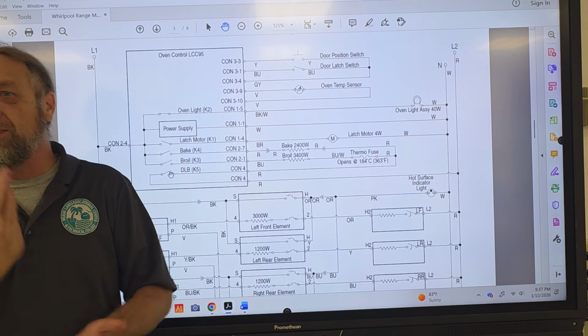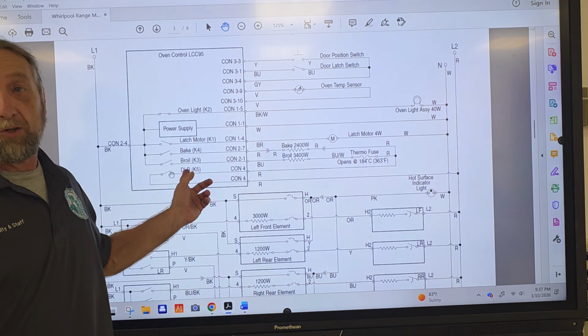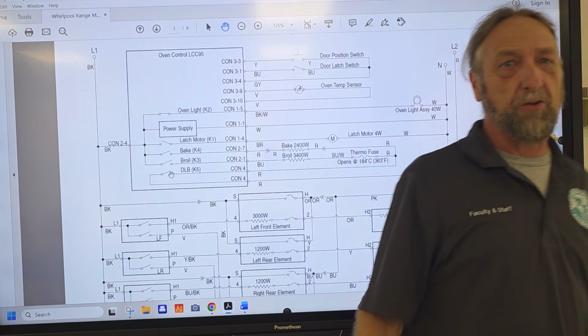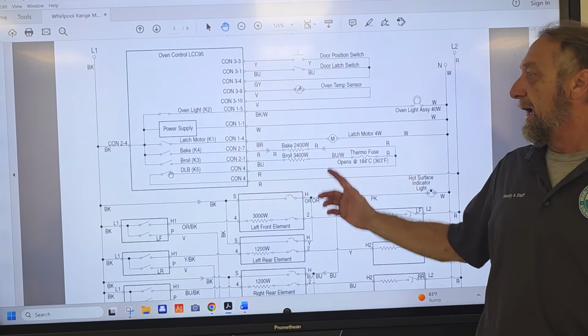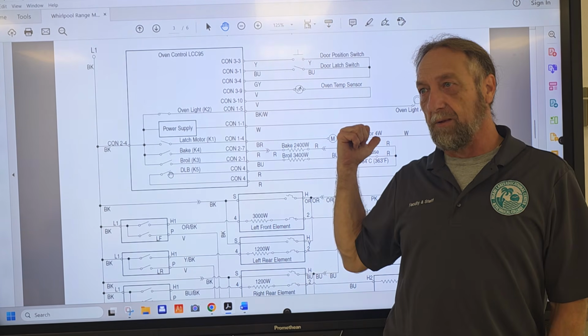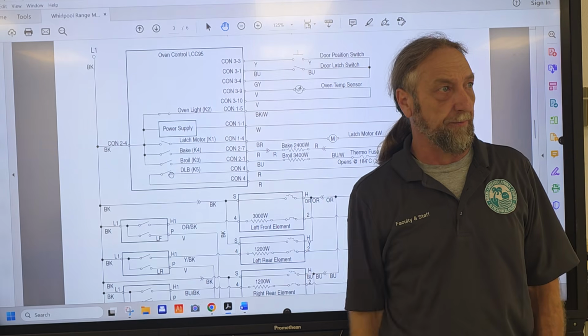Wow. So always unplug the machine for safety before you stick your hands in there. But electrical code, I don't know if it's UL or whatever, the Underwriters Laboratories who determine safety in electronics and electrical equipment, they said you've got to put a second relay on the other side of the element so that there's no power at the element when the oven's off.